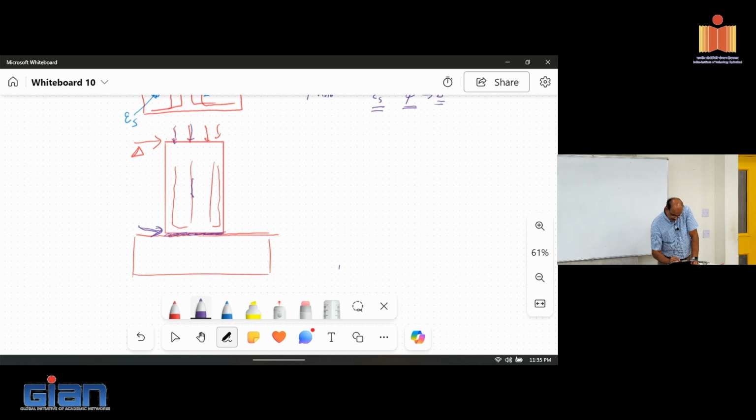Let's say this is the center of the vertical load. As you start pushing it, this is going to migrate towards the right side of the wall. As the wall starts to rock, your center of gravity is starting to move. Your compression is going to be somewhere here. Once you go past that centroid, the wall is going to tip, basically. So this is what's known as the free rocking structure. It's free to rock, but it has an instability problem.